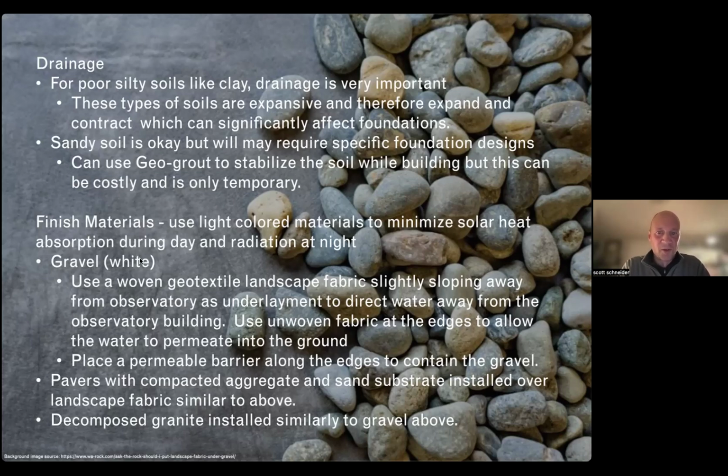And when you get out to the edges of the gravel, which you want to place maybe 3 to 5 feet away, and in fact if you're in one of these WUI zones, you really want to get it more like 5 feet away, you can use a nonwoven fabric to let the water permeate through it.